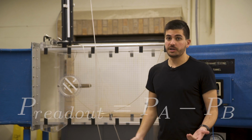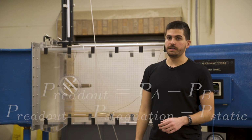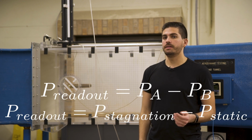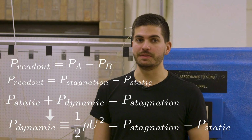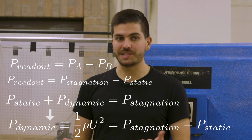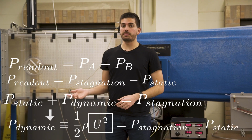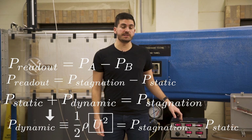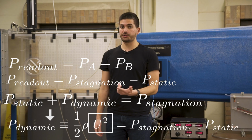So if we remember that the pressure transducer measures a difference of pressure, if we have stagnation pressure in port A and static pressure in port B, we're measuring the difference between the two. Using Bernoulli's equation, we know that this means that we're measuring the dynamic pressure. By doing this, we can determine the velocity of the flow. So when we have both ports from the pitot-static probe plugged into the pressure transducer, we're measuring dynamic pressure. However, we also need the static pressure alone.